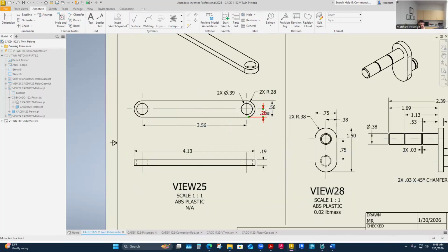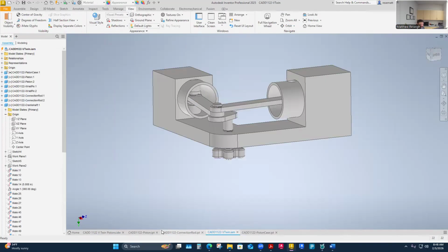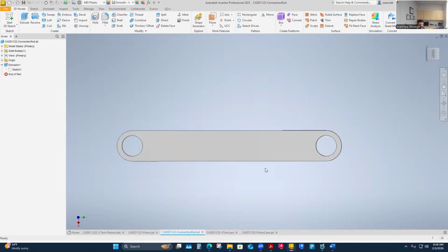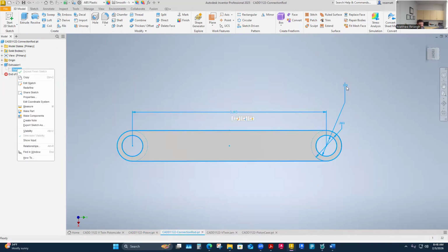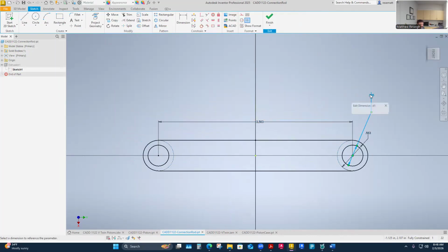So that's kind of why it is 10 thousandths more than 3/8. Sorry, I'll get to it eventually. So it ended up being the shaft size, which is 0.375 plus 0.010, 10 thousandths, for both of those holes.